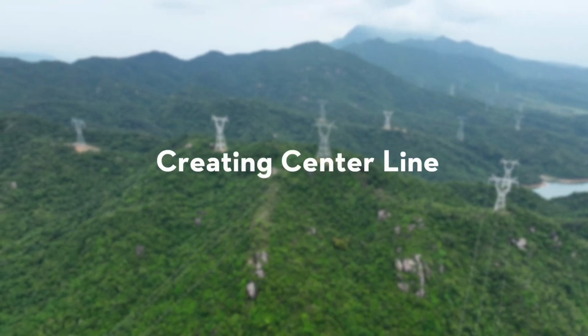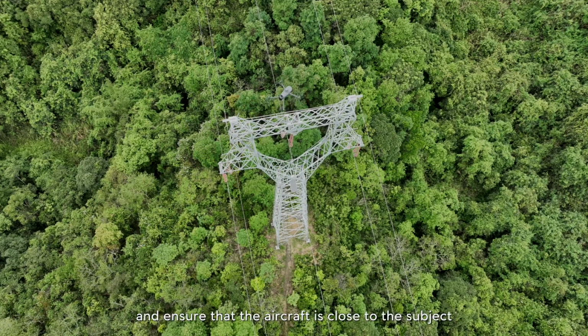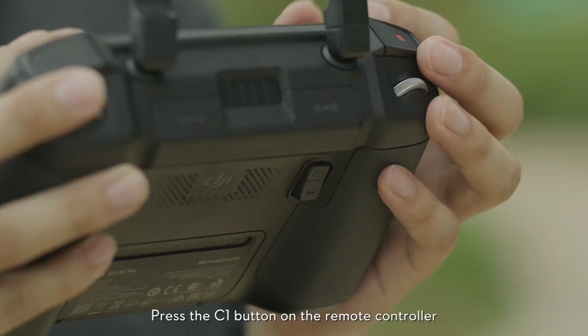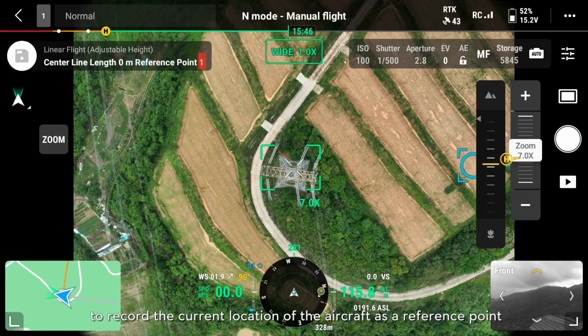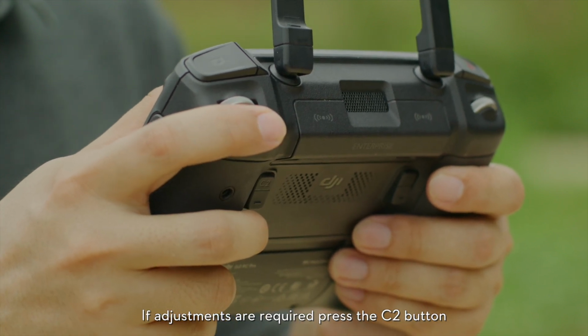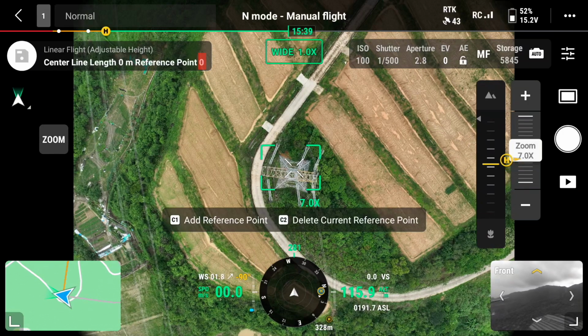Creating center line. Fly the aircraft to the area above the target subject and ensure that the aircraft is close to the subject for more accurate GSD and overlap ratio calculation. Press the C1 button on the remote controller to record the current location of the aircraft as a reference point. If adjustments are required, press the C2 button on the remote controller to delete the current reference point.